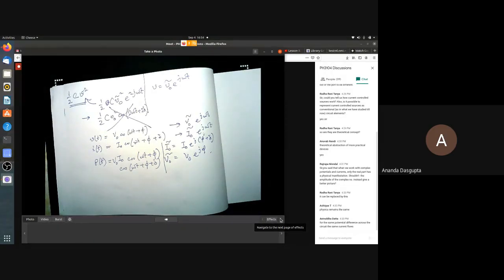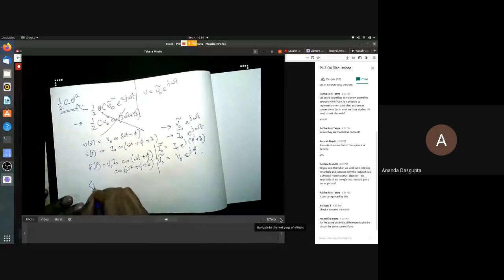The average power over a long interval is effectively the same as the average power over one cycle. If it's an integer number of cycles, then it's exactly the same. But even if it's not, if it's a very long time interval, then the extra contribution from a small fraction of a cycle sitting outside will essentially be negligible. So you average this over a cycle, and this is what you really want to calculate.